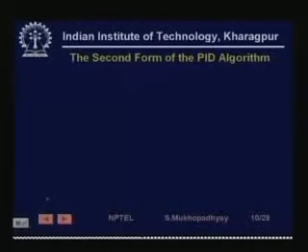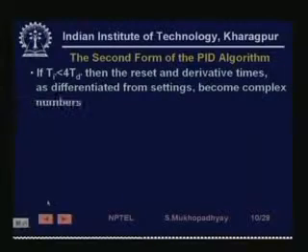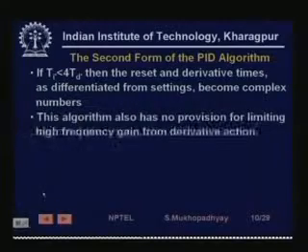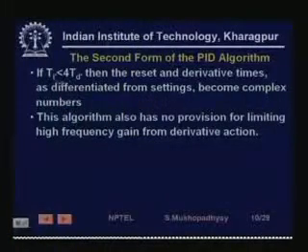All right. So, in fact, interestingly, it turns out that sometimes you get absurd readings. For example, if you set some value in the second form where Ti dashed is less than or equal to 4 Td dashed, you actually cannot set it in the first form, because if Ti dash is less than 4 Td dash, then Ti and Td values are complex. You won't get real numbers Ti and Td which will be able to realize this. So, you see the first form is somewhat constrained.